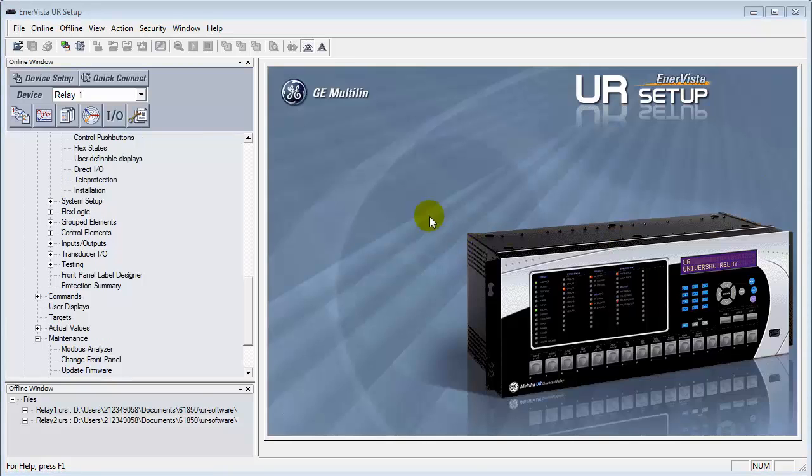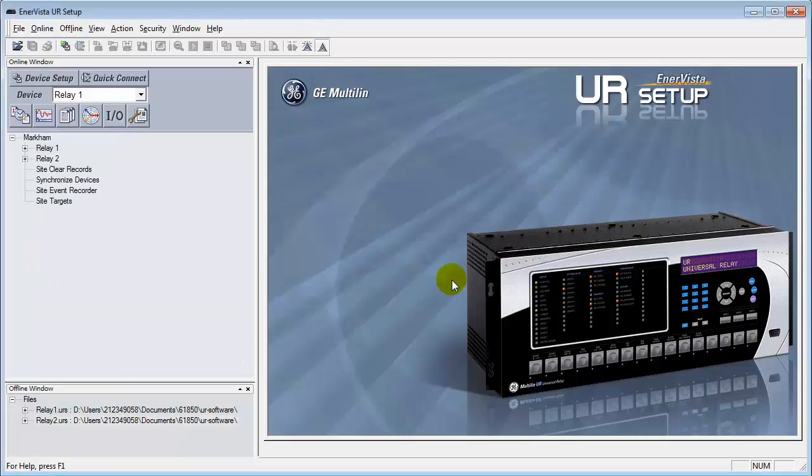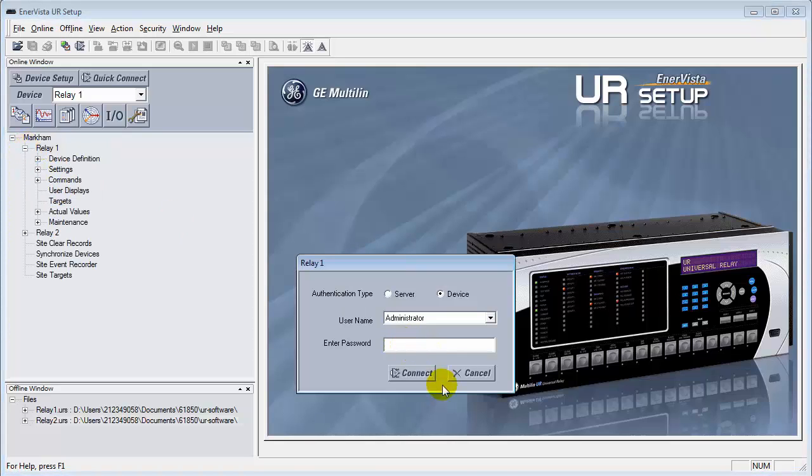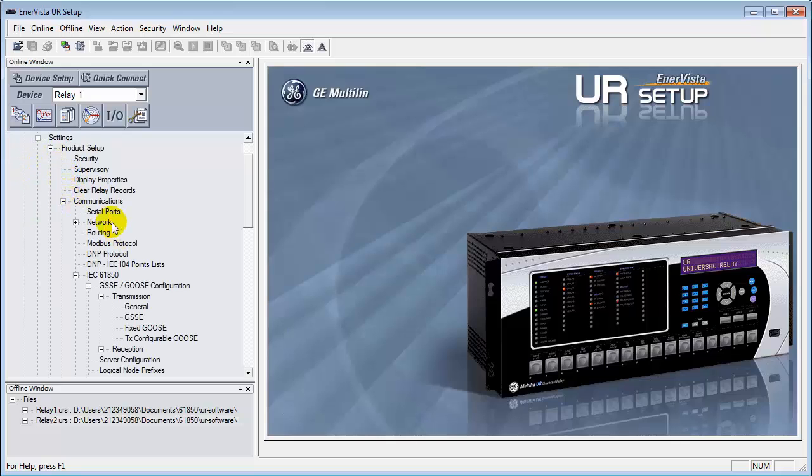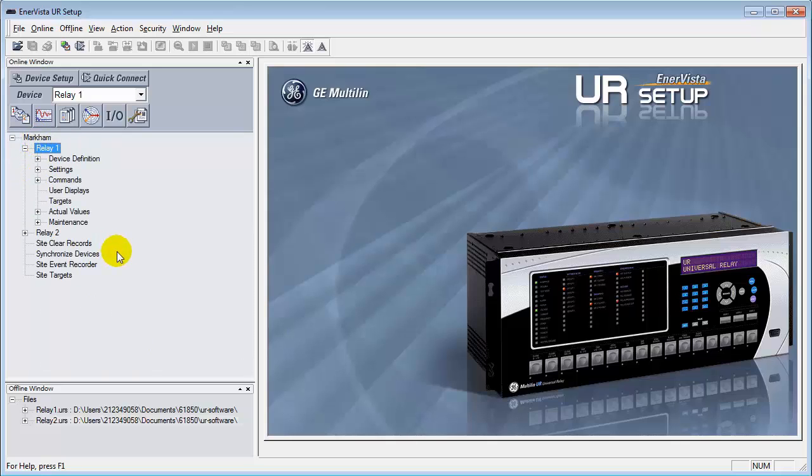Once the relay has rebooted, we can reestablish communications by selecting these icons on top. Initially turn it off, and then going back to this icon to switch it back on, and we should be back online again with the relay. This is change B1 hash mark for our cyber security on version 7. All right. That concludes the publisher side of the Configurable Goose for digital signals only.